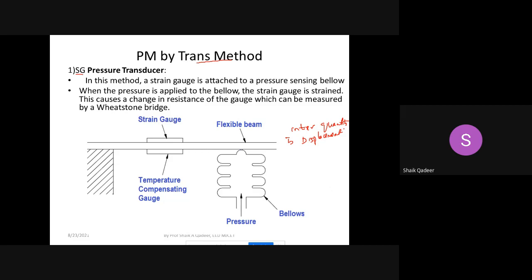We all know that. So this displacement causes some vibration. Agree or not? Yes, sir. So this vibration will be applied on this strain gauge. We learned this in unit 2. Then, sir, what happened? The strain gauge makes some changes in its resistance, which we can very easily measure with the help of Wheatstone bridge. This is the story. You need to use this figure and you need to write this information.